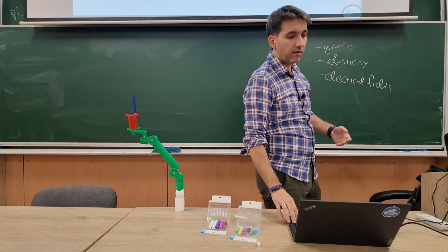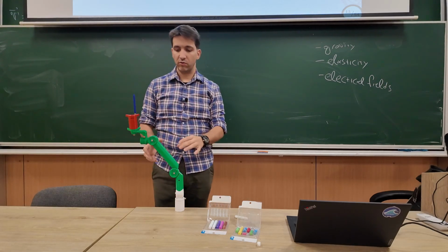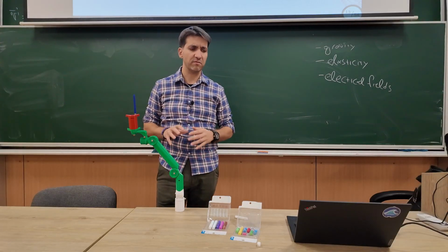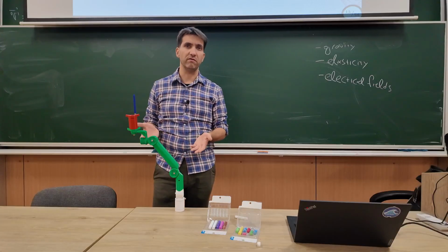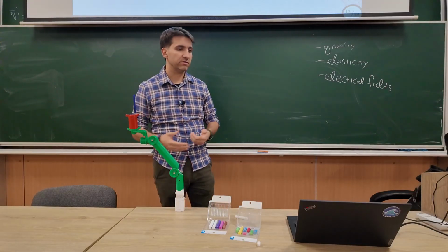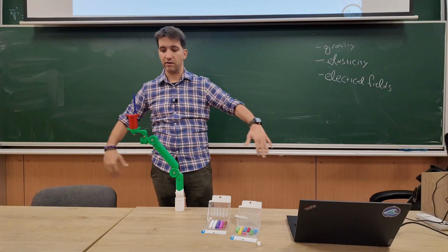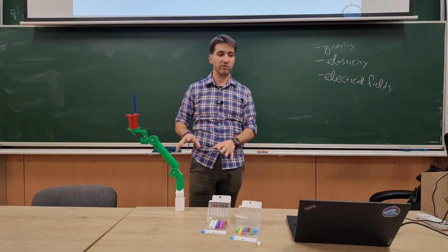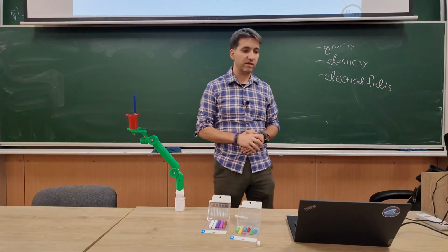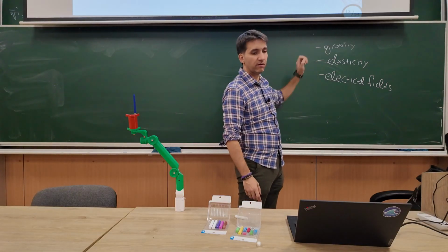So in general, for the types of robots that we will talk about, we neglect any elastic deformation. We assume the objects are rigid, so we don't have any energy stored due to deformation. That's an assumption, but it depends on the robot that we're using. It might be a very good assumption. If we have flexible robotics, for instance, it's not a good assumption because things deform. But if we have rigid robot arms, then it's good enough. And we also assume that they are electrically neutral, so there are no charges between the objects and the world. That's a much better assumption than the elastic one, because if these were electrically charged, it would be dangerous. So we typically ignore these sources of potential for robotics, but gravity is an important one.